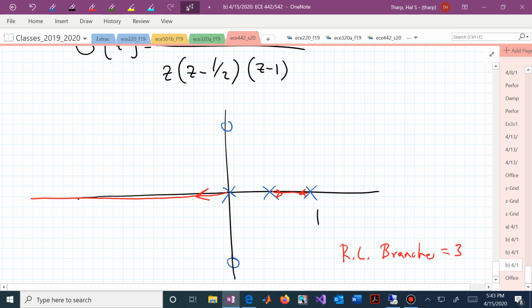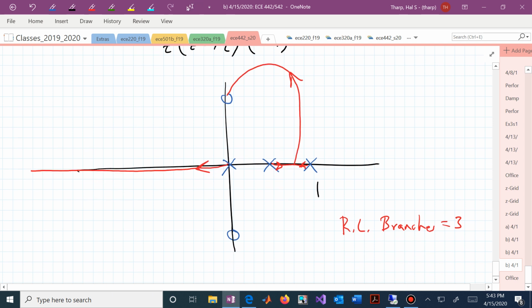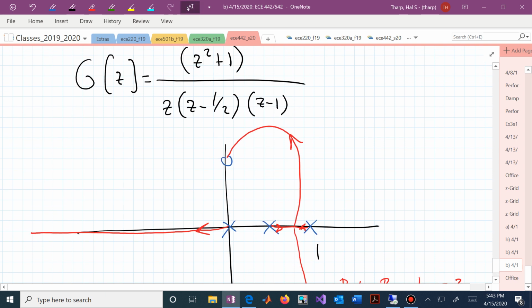What we want to know is how do these, we know how to figure out where they break away. That's the relative maximum between those two. Let's just say that they break away here. And now do they come in that way to those finite zeros? Again, this has to be symmetric. And we would then be calculating relative to this positive real line and this tangent line to the root locus, we would say, what's that particular angle? That's now our arrival angle.